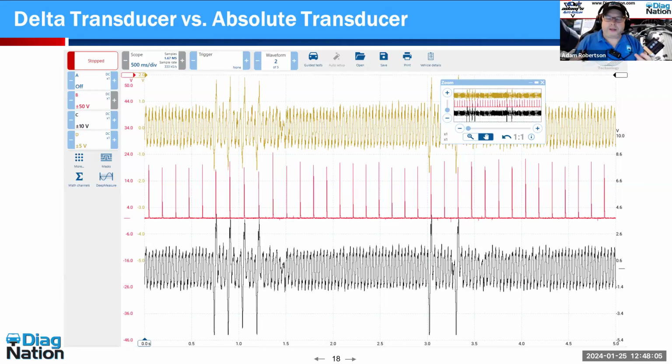But my point is, you're not going to use a piezoelectric pulse sensor to measure in-cylinder pressure. Nope, it won't work. You're not going to use it to measure hydraulic pressure. Nope, it won't work. You'll just blow it apart. So they have their own place and stay. The real difference is this one will typically work anywhere that this one will, but this won't work everywhere that one will.